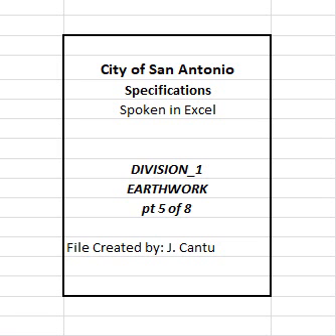Use approved rolling equipment complying with Item 210, Rolling, to compact each layer. The plans or the engineer may require specific equipment. Do not allow the loose depth of any layer to exceed 12 inches, unless otherwise approved.